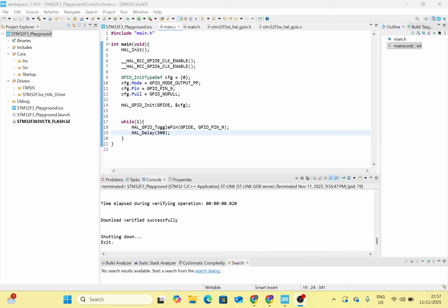One other thing that I want to talk to you about is the fact that you can de-initialize your GPIOs. When it becomes appropriate to do that is, let's say, for instance, you put your microcontroller unit into sleep mode, and you don't want any of the unused GPIO pins to consume power needlessly, then you have to de-initialize it. And the function for doing that is...